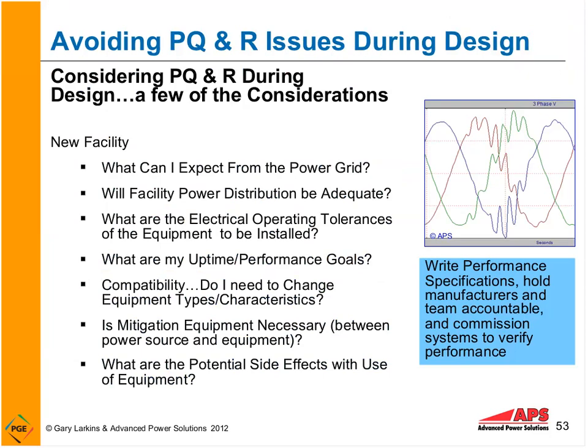So, avoiding power quality issues. We all want to avoid problems. So what we need to do during the design phase of a new facility, one of the things we want to know is what can I expect from the power grid? Will the facility power distribution system be adequate? What are the operating tolerances of the equipment to be installed? And this I must emphasize as a major important issue. What is the tolerance of the equipment I'm installing?